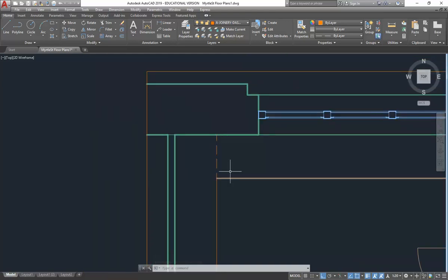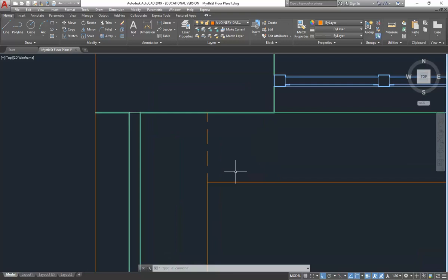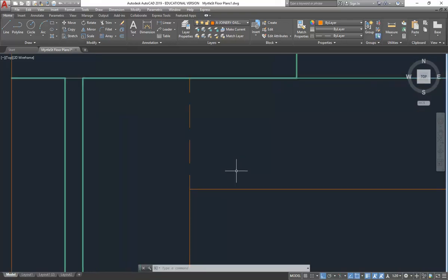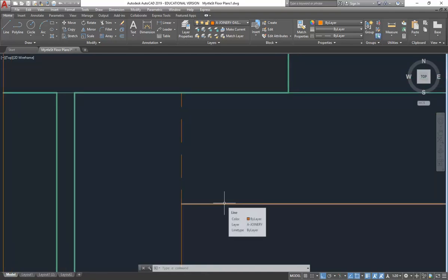Okay, so that's 600. Now I'm going to do it again a bit daggy and have a setback for my cupboards underneath the bench. And yeah, I know flush is really popular and flush can be good. It's more functional to have it set back, and there are lots of good reasons for it. You don't get things dripping on the doors. You've got a bit more room for your hands and fingers. But also people like the more slick look that you get with the flush things, I think. So flush is popular, and I've done a few.